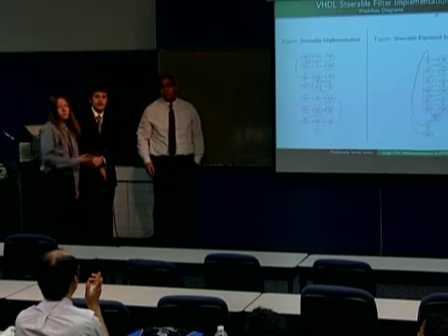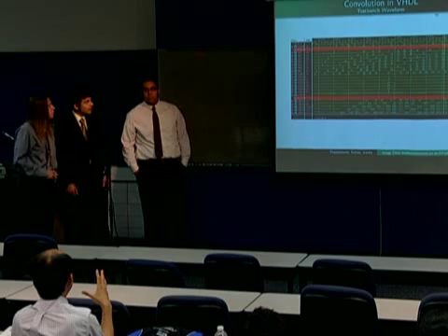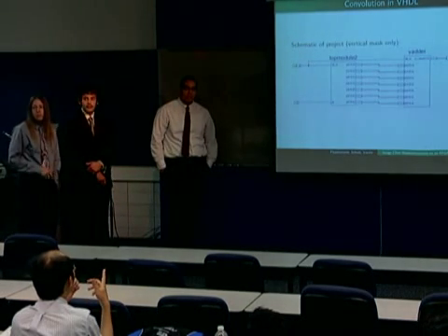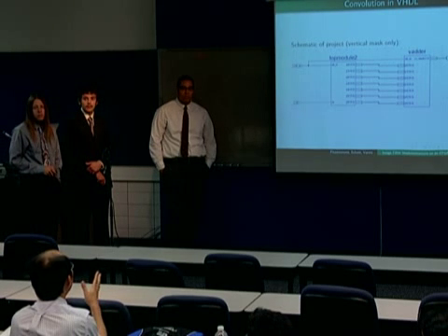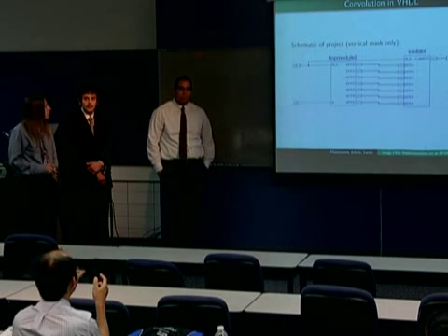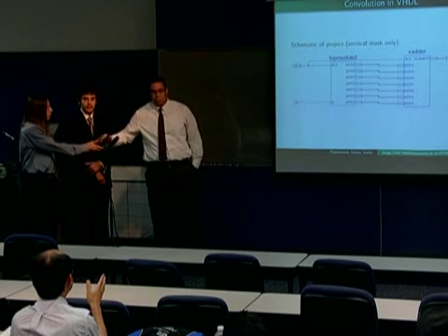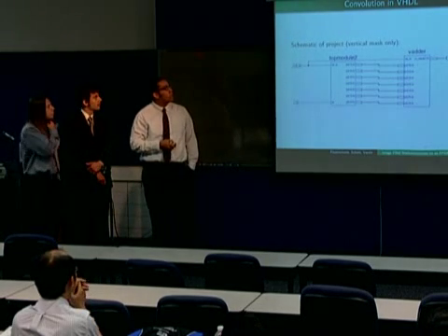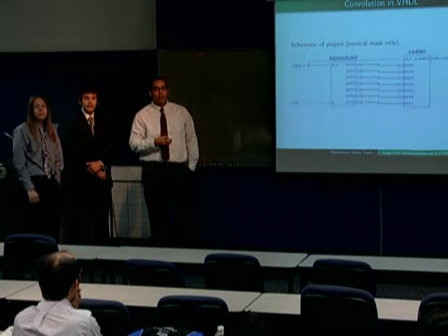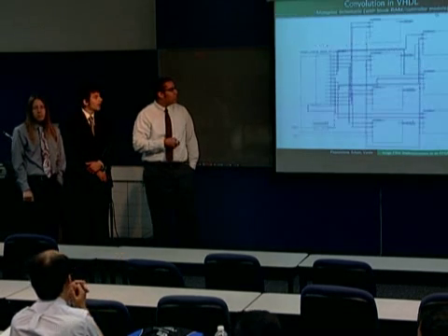Yes. One quick question regarding your previous slide. Are these schematics generated by the VHDL software? Yeah, it's the Xilinx software that generates them. How do I look at the output and see if that corresponds to your design? I just don't have a general idea how you look at the actual schematic and see if it exactly implements what you want to do. Basically, it'll output all our VHDL results, and you can write that to a file, and then compare that to what we did in MATLAB to make sure the results are right. Okay. Well, it's hard to really just see the schematic. Yeah, it's a little hard.